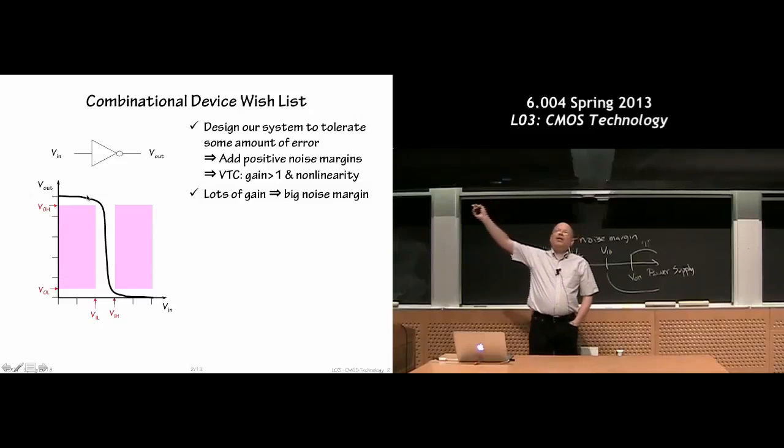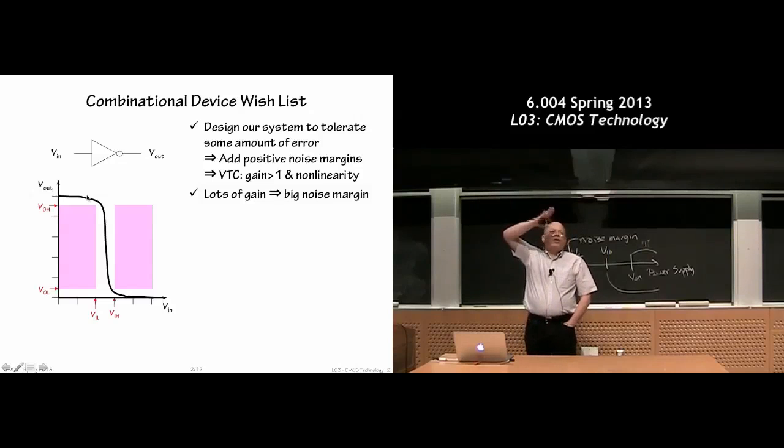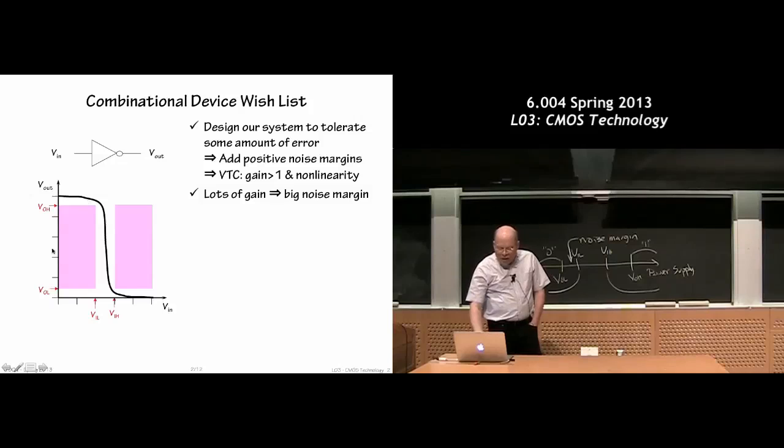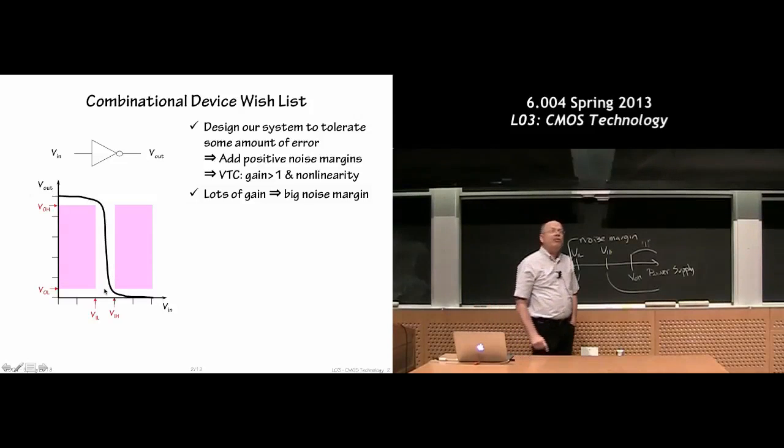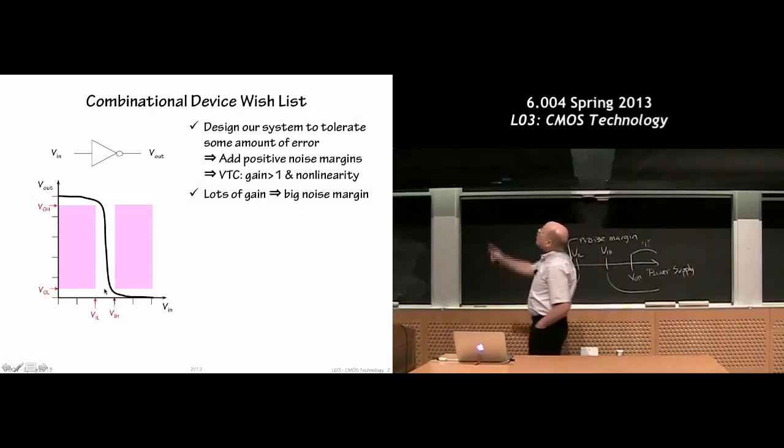How is that reflected in the graph? Graphically, how is gain represented? It's the slope of that curve. As the slope gets steeper and steeper, the device has a big gain. In other words, if I make only a small input change along the x-axis, you can see the output voltage changes dramatically. It falls precipitously. So that device has very high gain in that region.